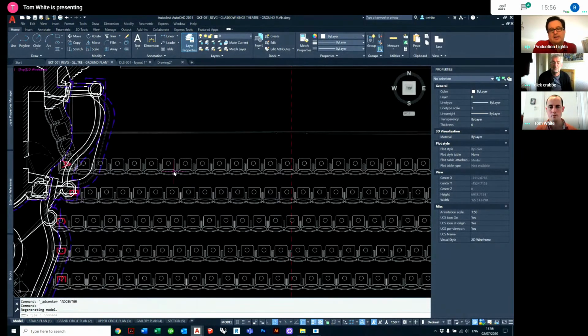Cool, and you can also, say if you're working for a different company, you want to drag a layout in, you can literally just drag it from Design Center onto the drawing and just drop it, and it will insert, and it'll be the same for blocks and things like that. And it's an amazing way of bringing dimension styles over or text styles into a new template when you're working in a new company. Yeah, definitely. I think everyone should get their heads around Design Center if you're a Windows user.